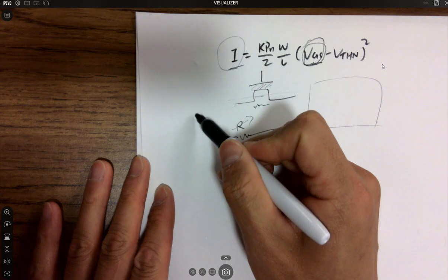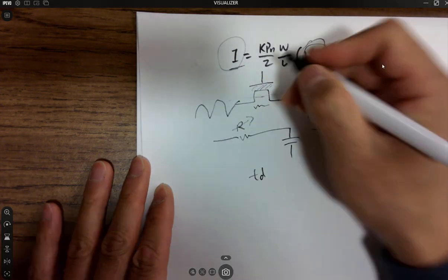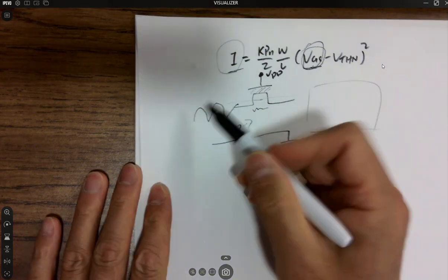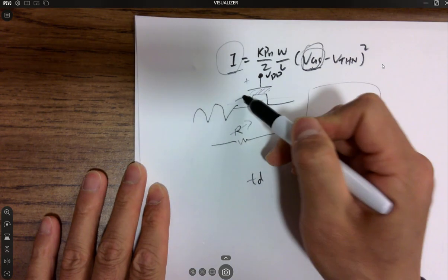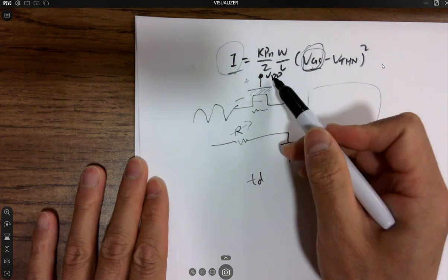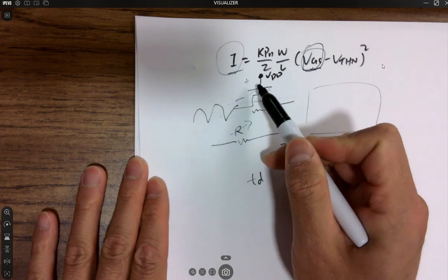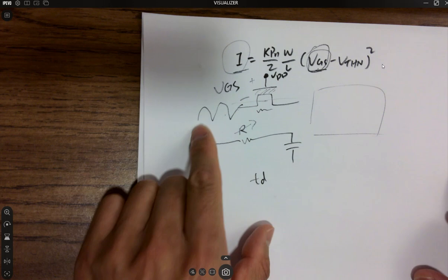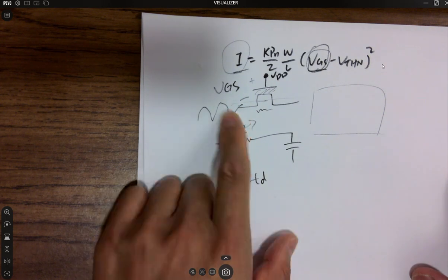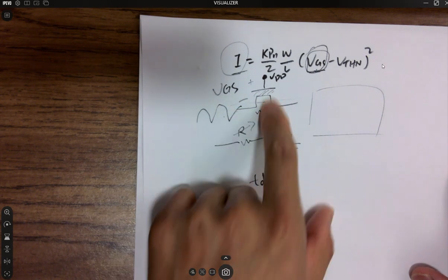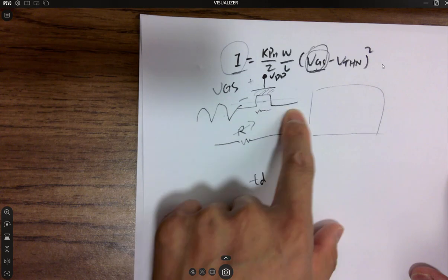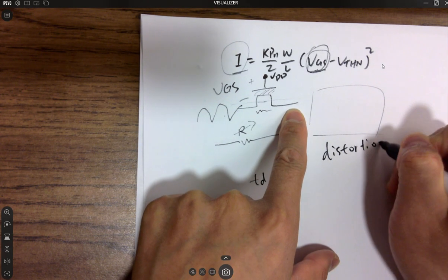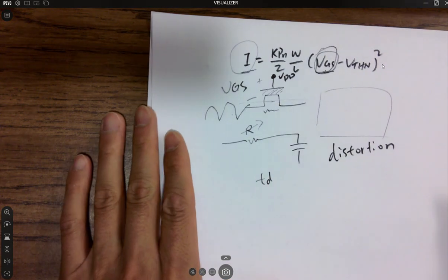If I have an analog signal over here, and I tie this point to VDD, right? Because this is changing, your VGS is changing. VD is not changing, but this is changing. So eventually your VGS is changing depending on your analog signal input, and you are getting a different time delay all the time. So eventually it causes distortion of the sampled voltage.